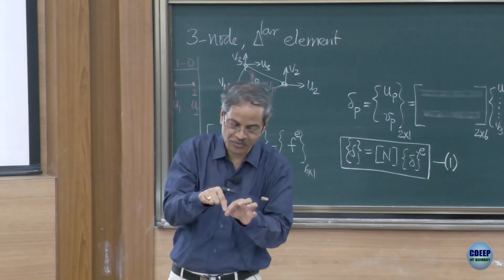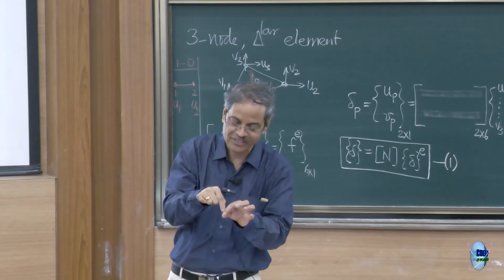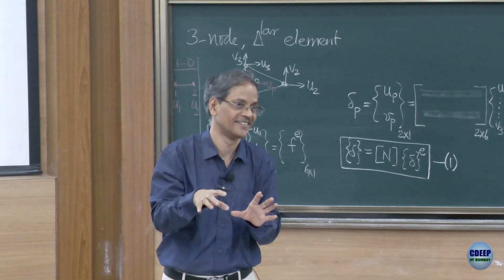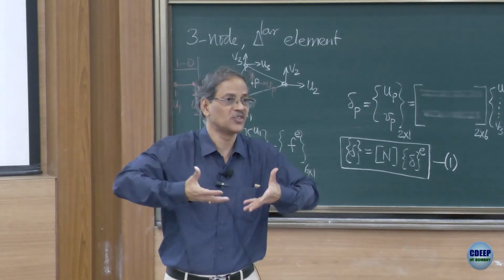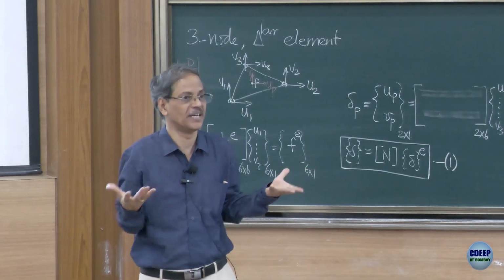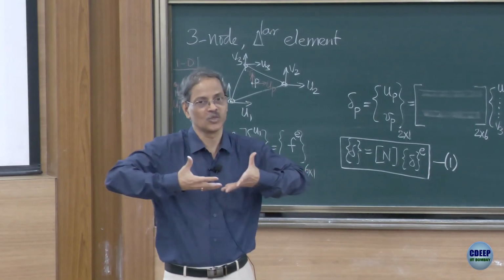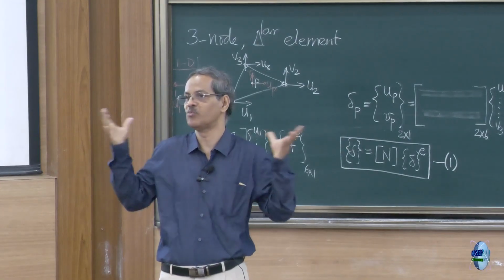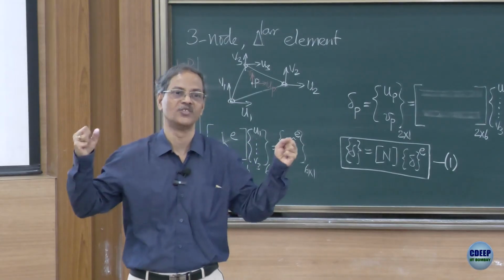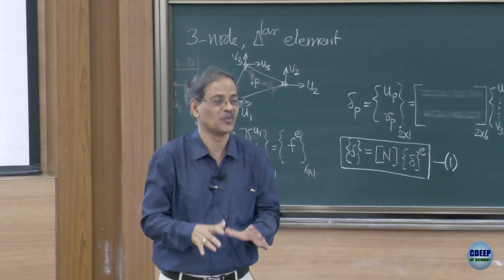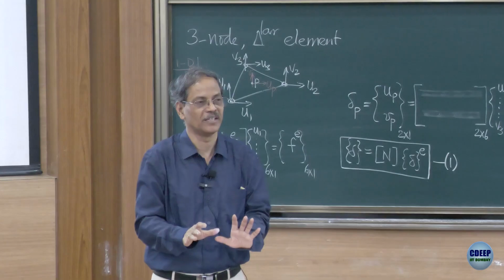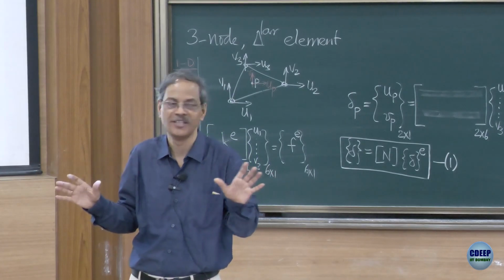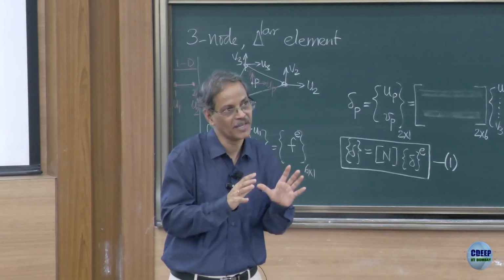With this strain field and stress field, there is a certain strain energy in the deformation of the element, because the structure behaves like a spring. When it undergoes deformation, it stores elastic energy, and when the load is removed, it gives you back. So, our fundamental assumption, because we are doing linear analysis in structural mechanics, is that it is purely elastic. So, it will come back to its shape.